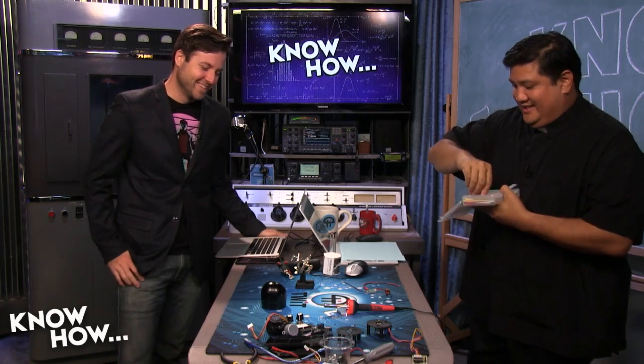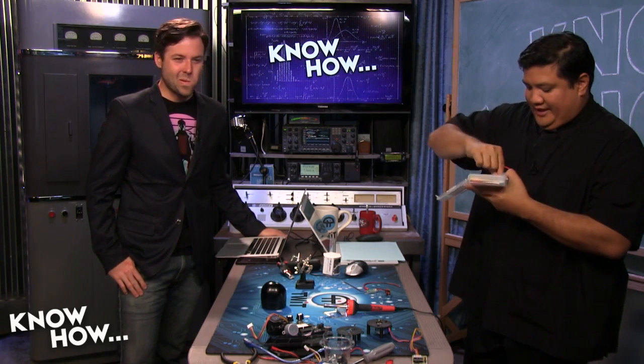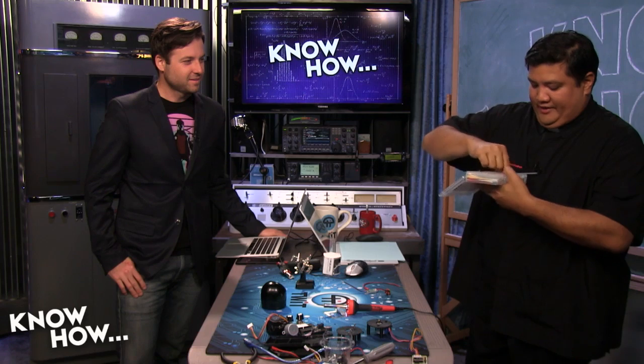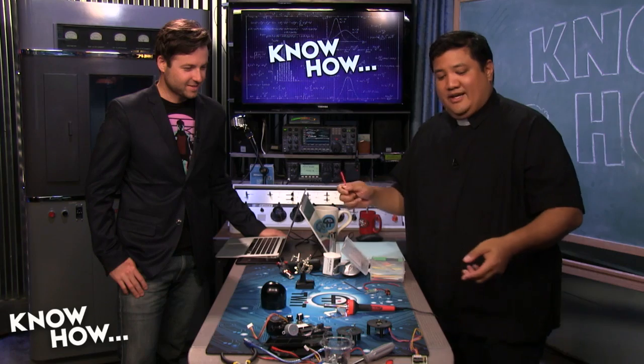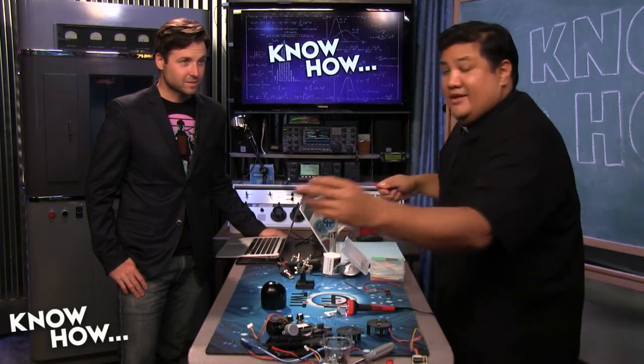It's union rules. All right, so I need some heat shrink so that I can protect this after I've soldered them together. Let me repeat this, and it's going to sound silly, but everyone who's ever done any sort of electronics is going to know this. Solder once, measure never. Put the heat shrink tubing on before you solder.